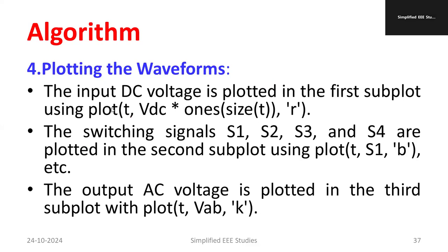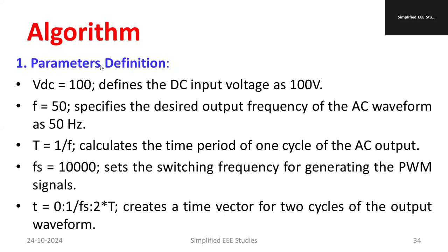Now, plotting the waveforms. Here you need to use subplot. You have to show the switching signals as well as the output voltage. So these are the simple algorithm steps concerning the MATLAB design of single phase full bridge inverter.